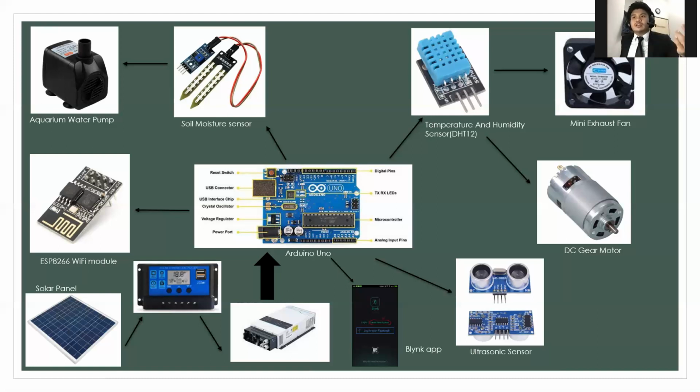The ESP8266 is a low-cost Wi-Fi module from the ESP family that may be used to control electronic projects from anywhere on the planet. It has Wi-Fi, so the module can communicate with the Wi-Fi signal using the TCP/IP protocol stack. Because the module's maximum working voltage is 3.3 volts, you can't use 5 volts, because it will damage the module.